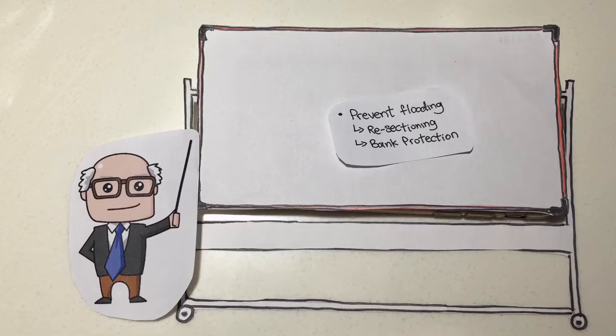In some countries, concrete structures such as gabions and revetments are built along a river channel to divert the flow of water from the river banks to the center of the channel. This protects the river bank from being eroded by the force of running water, therefore reducing the amount of sediments that flows into the river. When there are fewer sediments washed into the river, the capacity of the river to hold water increases. When this happens, the river channel will flood less frequently.